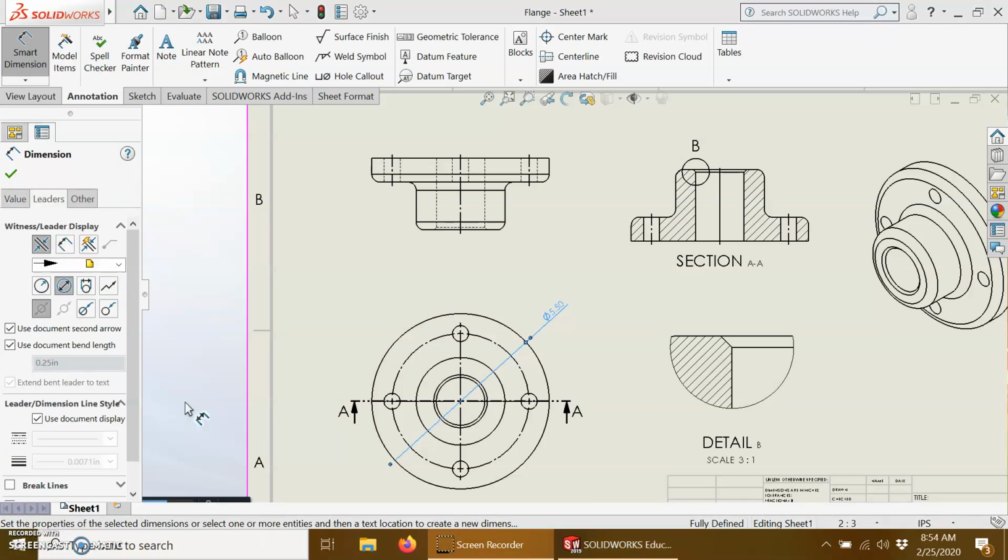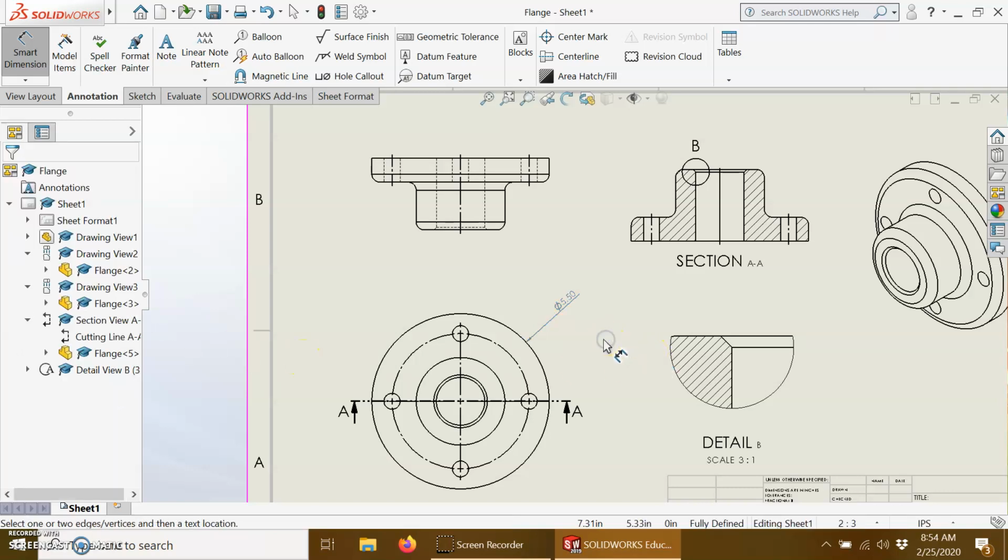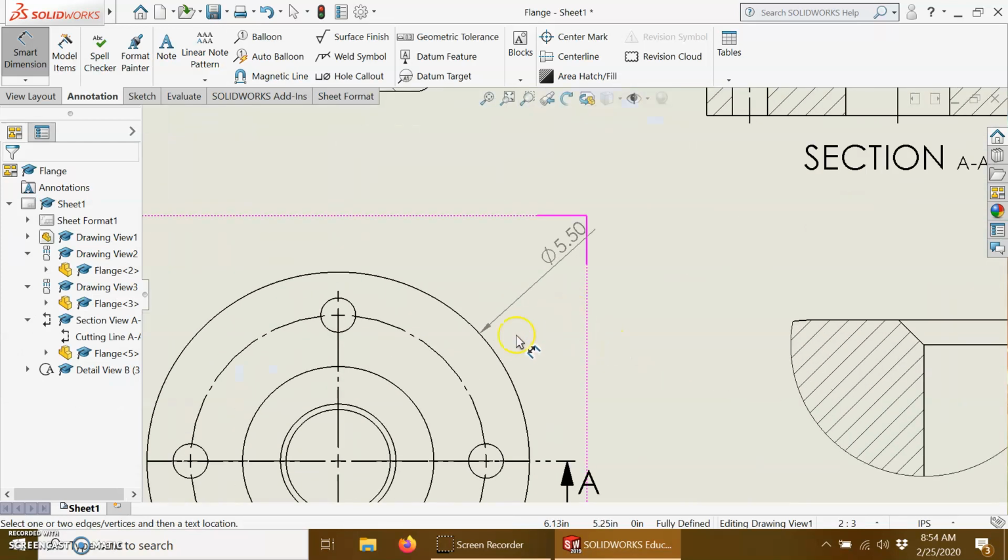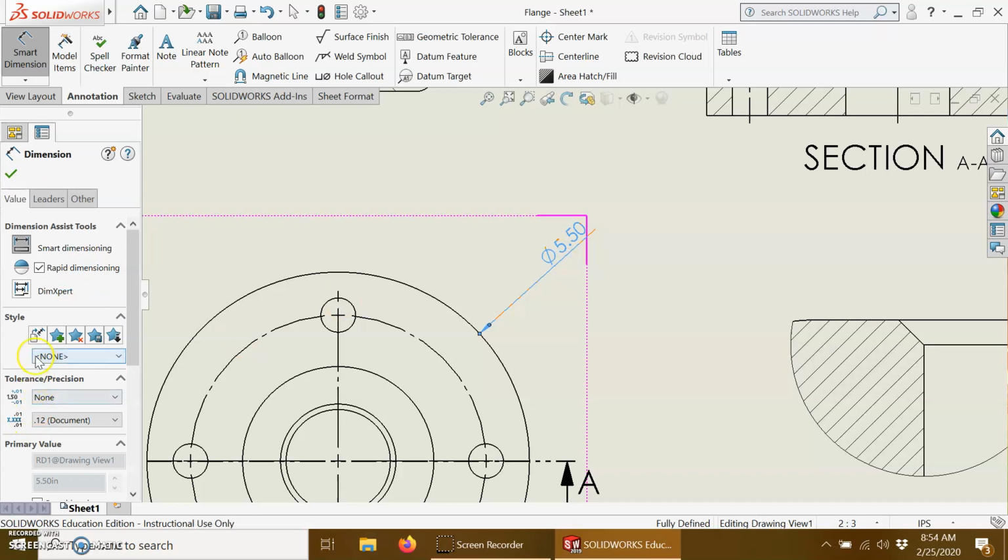As we're looking at this, if we keep this dimension in this frame, dimensions on the inside look a little bit messier. So if you look here with the leader lines, you've got a bunch of different ways you can do it. Typically I like having it here where we're dealing with just the leader on the outside. And so you can see that dimension comes and it points right to it.